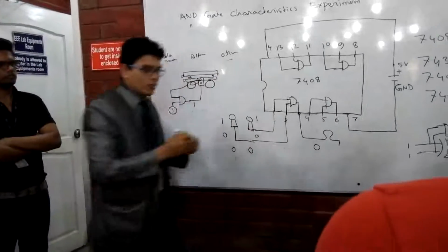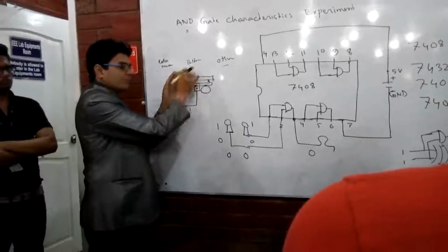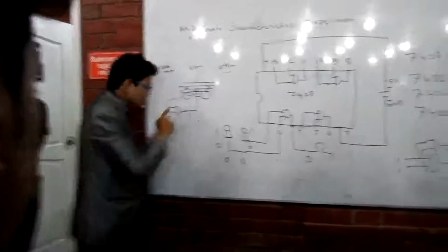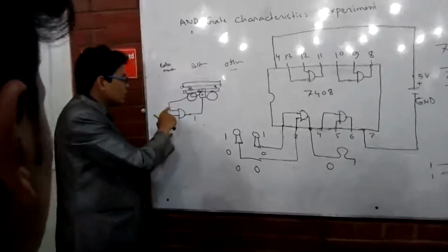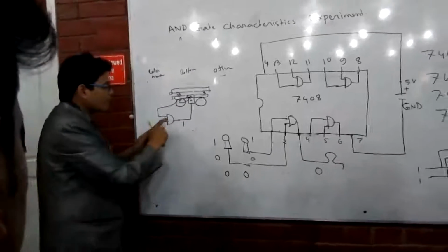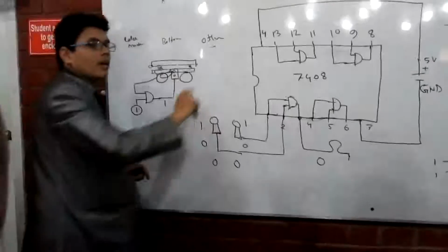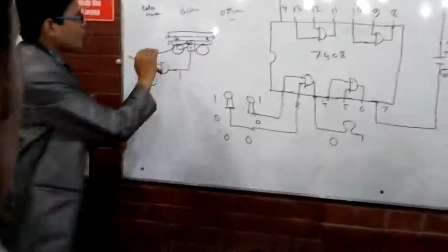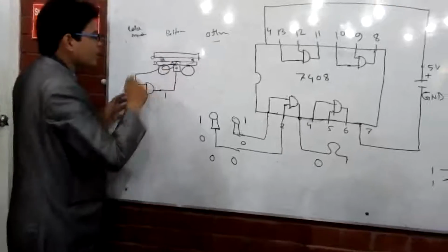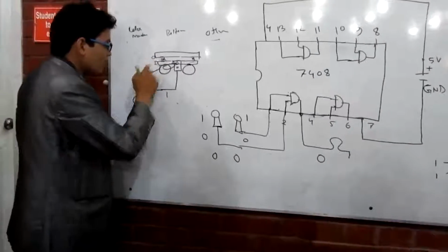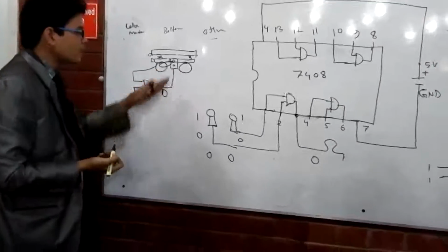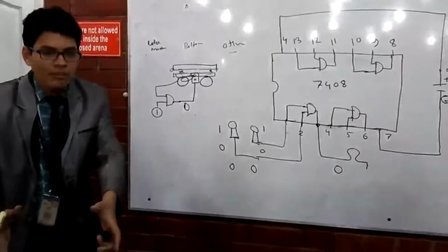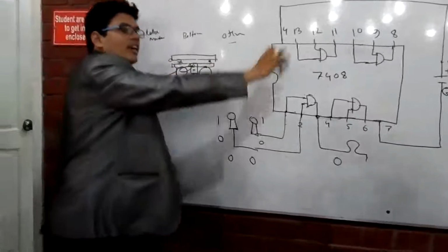And the motor will run. So when I put some clothes over there, with the weight of the clothes it will get down. It will make this portion 1, and this portion is already 1, right? Do you understand? Yes, sir. That makes the motor run and the tray will run. At the other terminal, when other people take up the clothes, this will come up because of the spring, and it will become 0, right? So 0, 1 makes 0. That doesn't make the motor run, and it will stand there. Once he finishes his job and puts the clothes over there, it will run again in the same way.